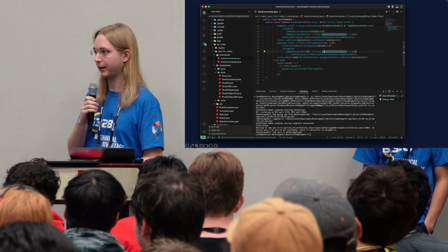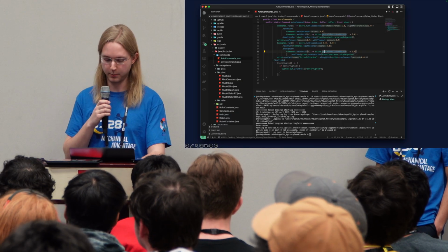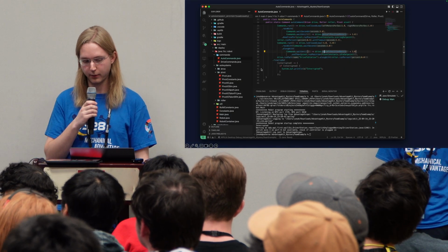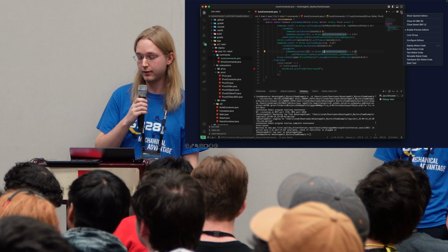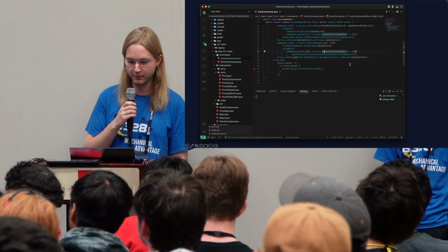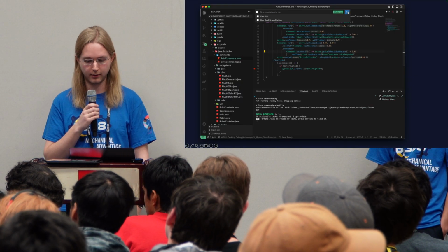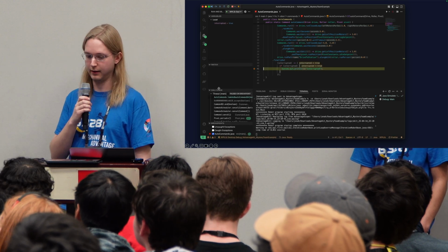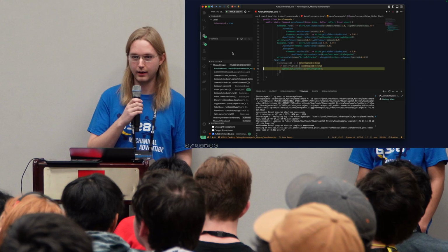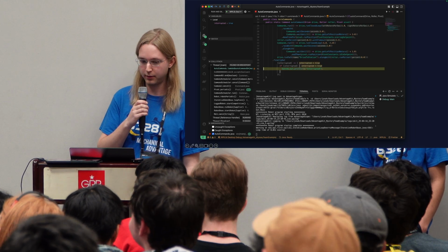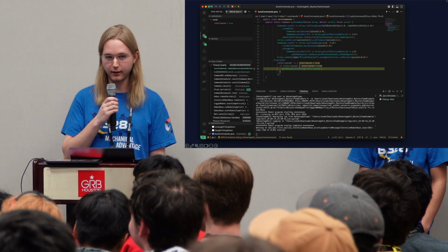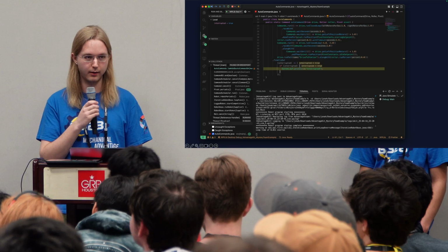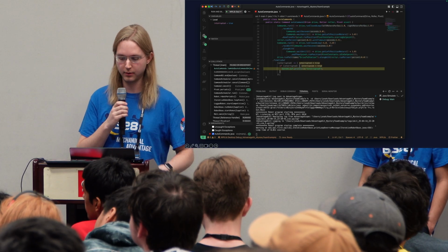And in this new callback function, what we're going to do is add a breakpoint. Let's watch. So we'll add a breakpoint at that line that's executed when the command is interrupted, and then launch the simulation with log replay. Just like before, except VS Code will pause automatically when that line is executed. And it gives us a whole bunch of data. Among other things, you can see here is the call stack of all of the methods that are being run in order to reach this line of code.